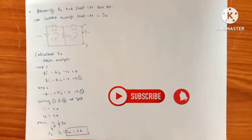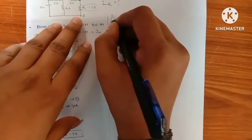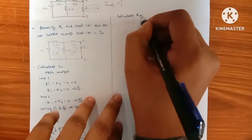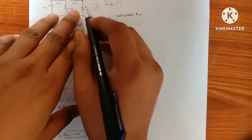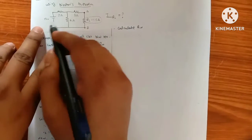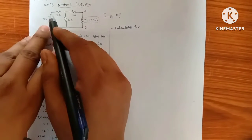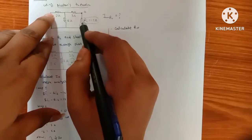Therefore, after calculating IN, the next step is to calculate Rn. How do we calculate Rn? We should remove RL and replace the sources with their internal resistance. Here we have a voltage source, so we make a short circuit, and here we make an open circuit.